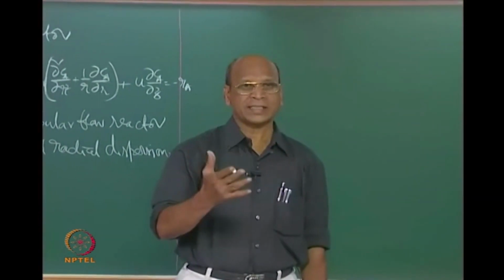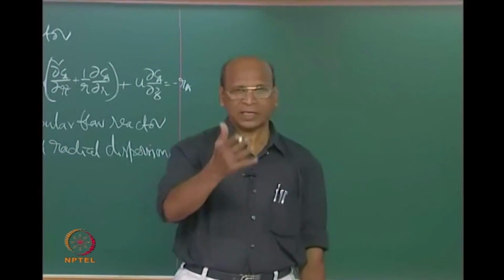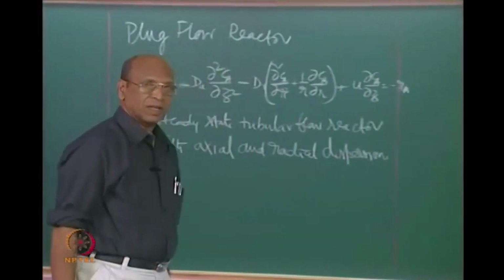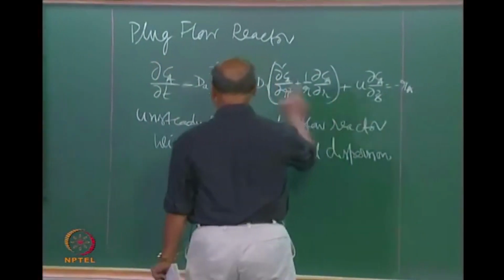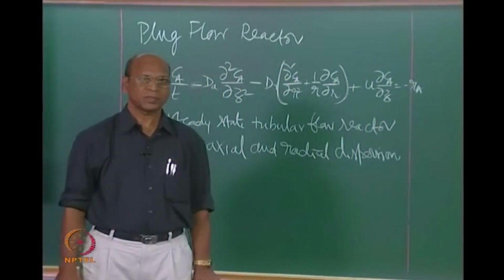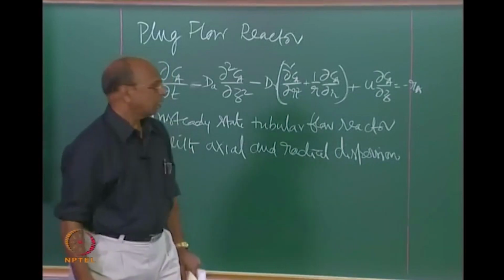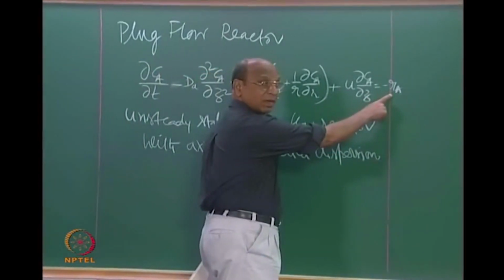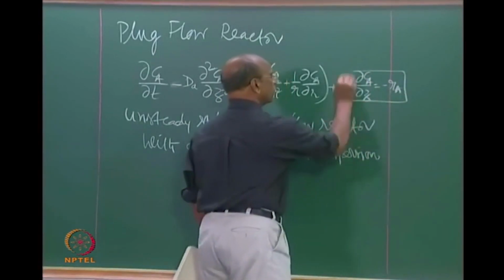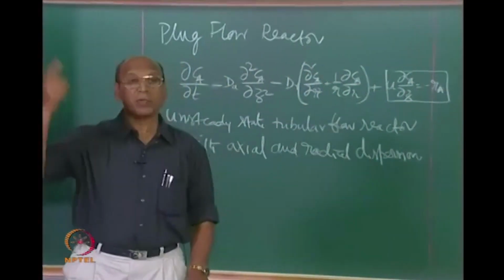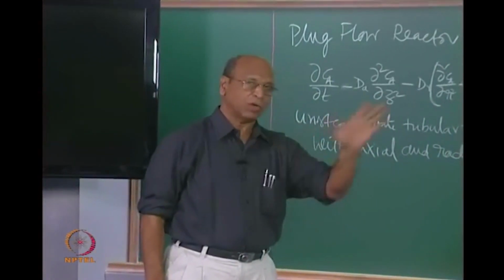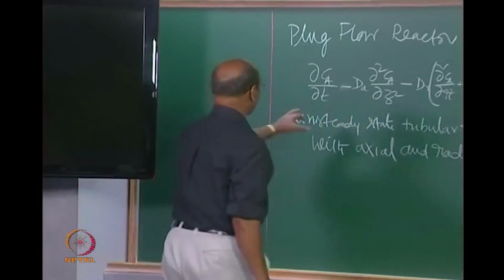I told you all reaction engineers are steady state people. Correct, no? Now, where is the convection term there? Okay, this term. So, out of all these terms, how many terms have we taken, and what are those terms? Minus Ra and u dCA by dz. That's all, only those two. You see how much simplification we have done. So we said that unsteady state I am not bothered about because I am only a steady state guy. So this term has gone.